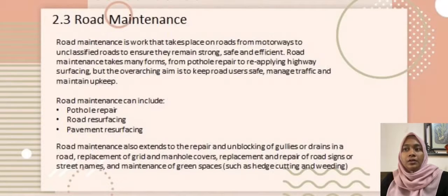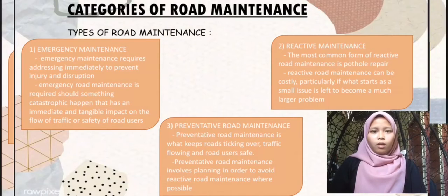Road maintenance also extends to the repair and unblocking of gullies or drains in a road, replacement of grids and manhole covers, replacement and repair of road signs or street names, and maintenance of green surfaces such as hedge cutting and weeding. Okay, today I want to present about categories of road maintenance.